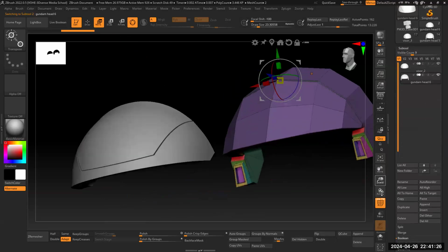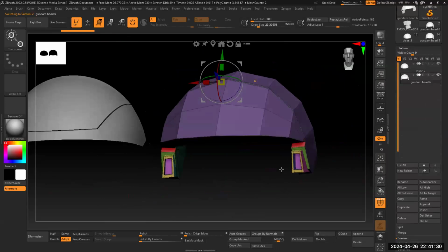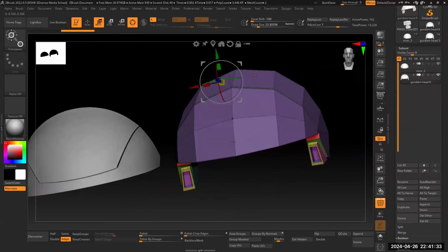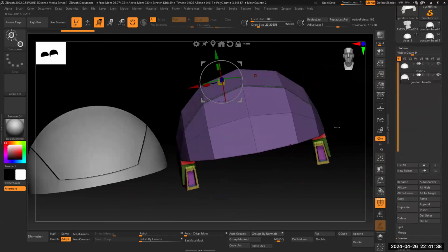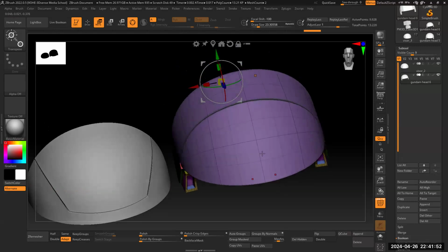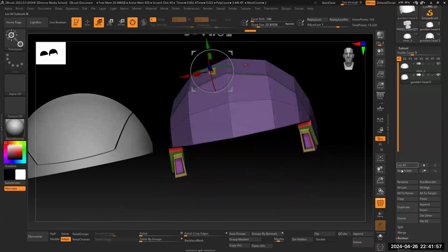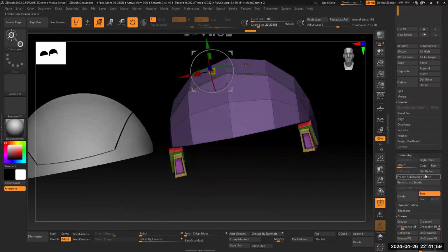So this one I built, I think it's clear to see that I use whatever I taught just now to build the basic shape, right? You start with a cube, then you stretch it out using the move tool or extrude, and then you just inset and subdivide or whatever it is. After I've done building the basic block out in ZModeler, that's when I tend to move up into the higher resolution and do these things to smooth it out. So let's actually delete all the levels so we can see how we're going to get it smoothed.